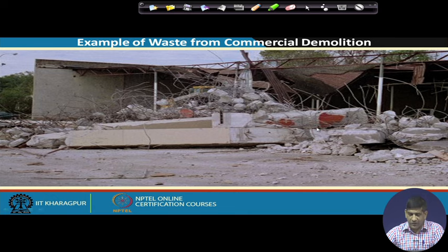As you can see over here in the demolition, you have some of this concrete. You have lots of rebars. If the rebars can be taken out, and rebars are your reinforcement bars, so if that can be taken out, it can be recycled as ferrous. Concrete can be used to make new concrete out of this. Concrete can be crushed and used as a filling material. So all those different types of applications can be done for that.